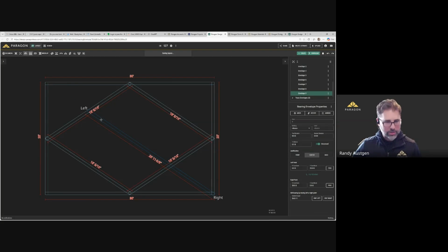So with that in mind, I'll just hit undo there, and I'm going to do this again with the shortcut key. So I had selected the bearing initially. I right-clicked, trim extend, and this is another huge time saver here. That was actually the first time I had ever done that, I think. I typically will hold down the shift key, and now we have our cutting options. So you can cut back to wherever you want it.